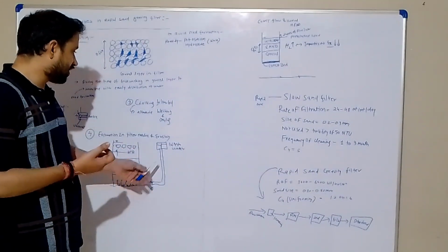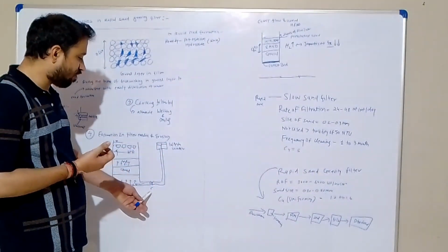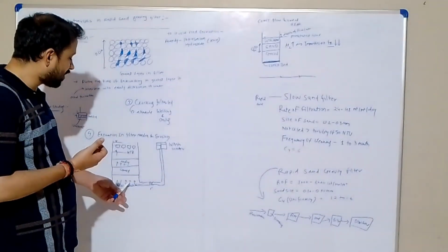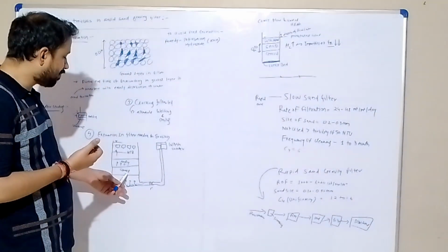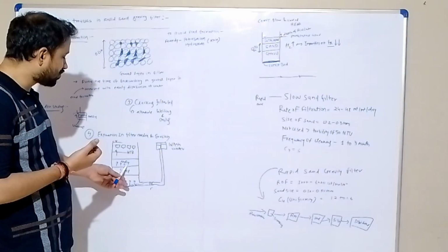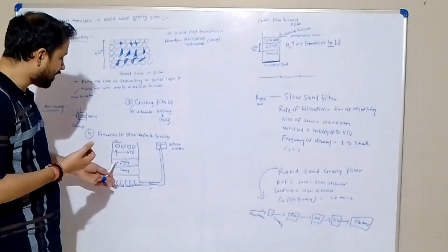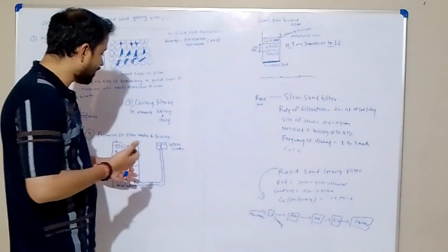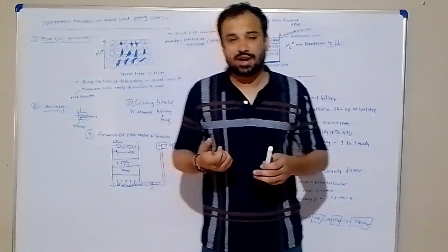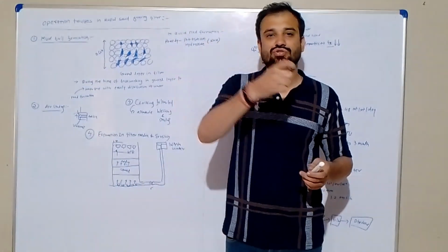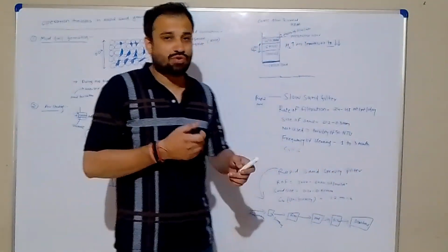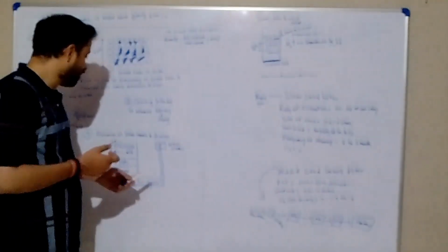When backwashing is done from valve number 6 through the lateral and the main pipe, the flow is provided in the upward direction, passing through the gravel layer and then through the media of the sand layer. As wash water, the impurities are dislodged to valve number 2, and from valve number 2 to the wash gutter.